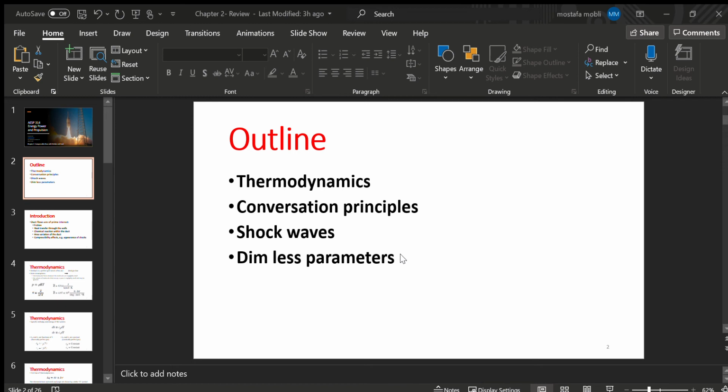If you make the uniform flow assumption, we can reduce the conservation of energy to this: the shaft power, the changes of heat within your system, the generation or heat loss within the system, and whatever energy is going out minus whatever energy is coming in.